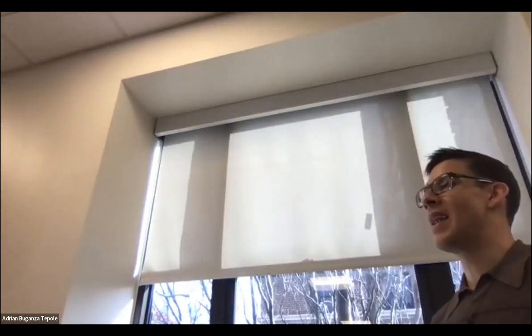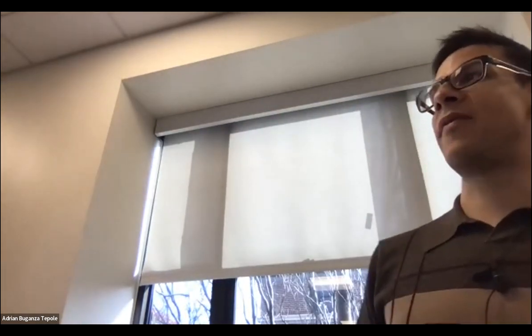If you do that, then the stiffness matrix is going to be BE transpose times BE. That's a little bit more efficient, but either way is fine. This B transpose B is doing the exact same thing that I'm doing. I'm writing out all 16 entries, but B transpose B would do exactly the same.